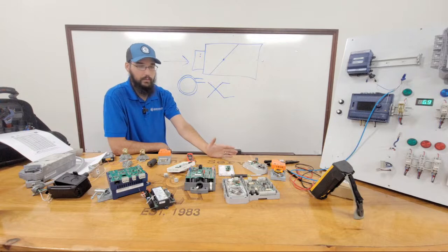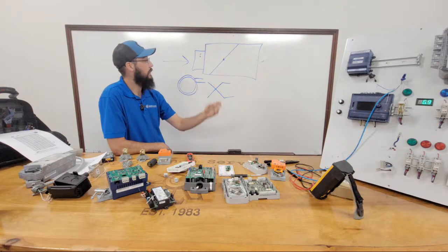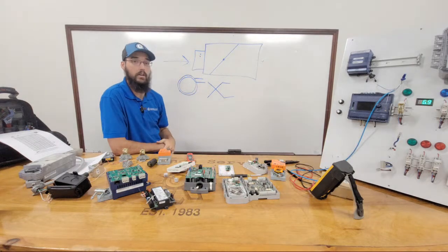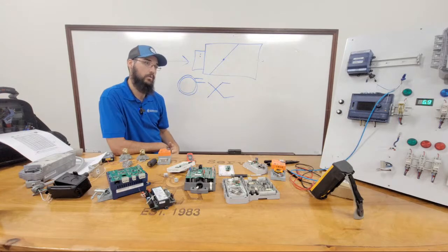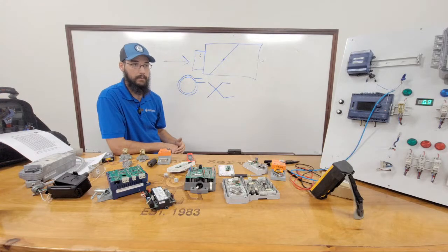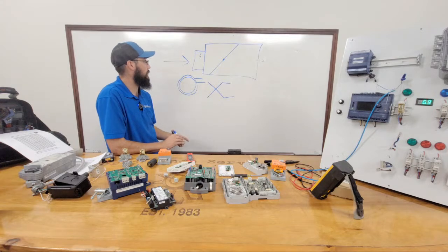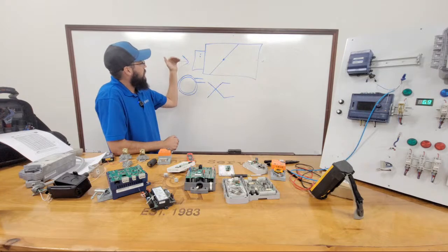If you're struggling to get the readings you're looking for, you might really try to verify. Now, don't take, I have run into them where the high port was the other way around. So don't just assume that every single one of them, the high port's going to be on top. Just a word of caution there.